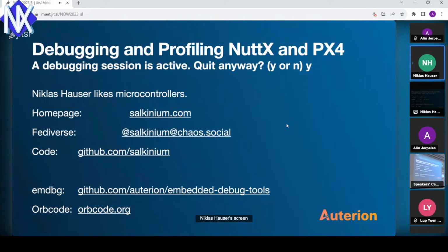I haven't tried it myself. So GCOV implements a hook inside the firmware, and then it outputs this over a serial line, which works well, but unfortunately it makes your firmware 2 or 3 times the size just because it needs to log every function call. You get the information out of the Orbtrace. How that's visualized, I don't know yet. It's definitely possible to do that.